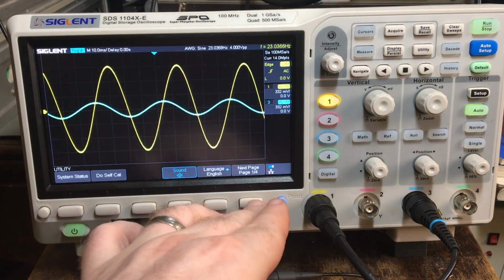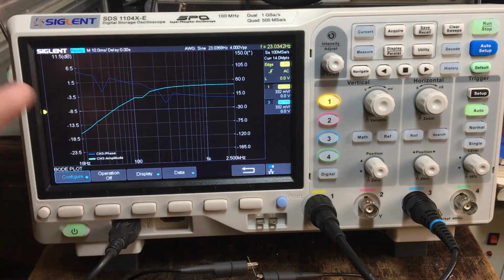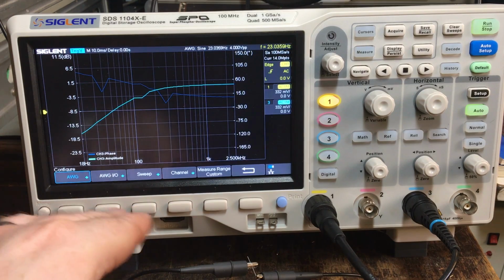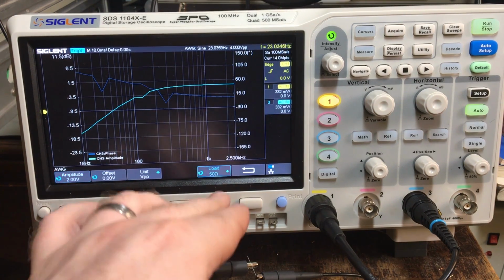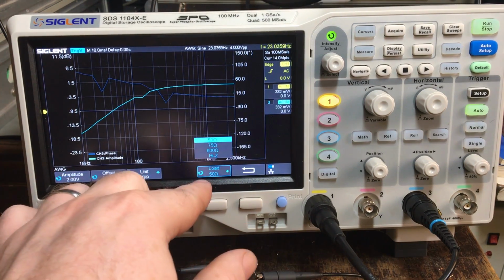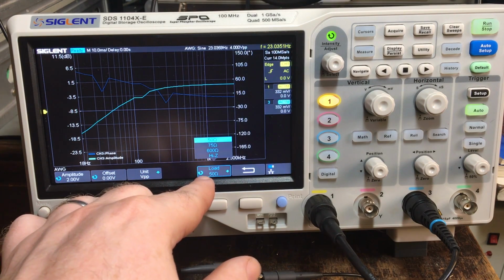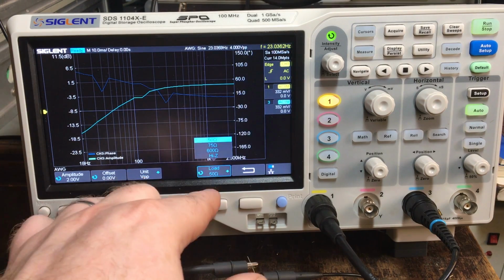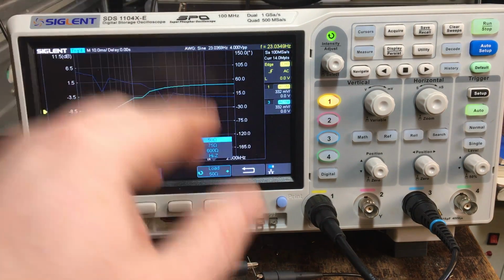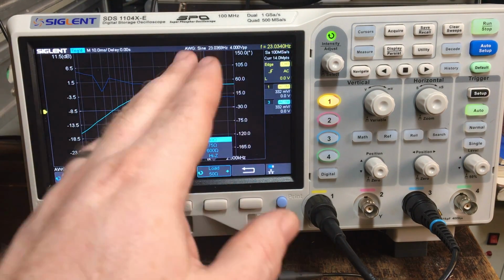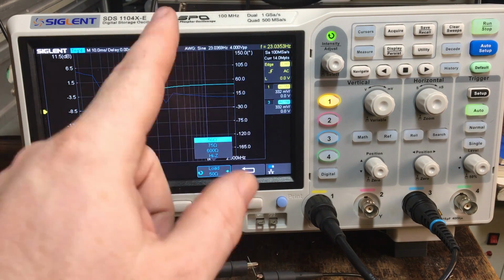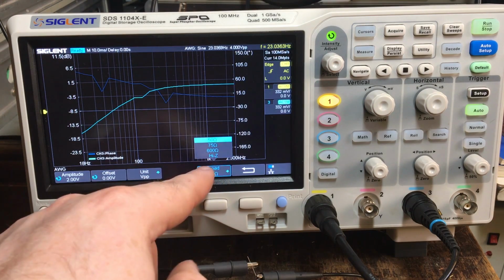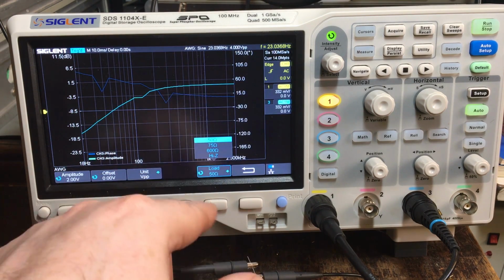There may be a reason for that, or maybe I'm missing something, but that's my understanding right now: if you're trying to set this load option, although there are multiple options here, and there's even an adjustable one here, in theory you can set any value between 50 ohms and infinity, high Z. But it doesn't actually take that setting. 50 ohms takes and high Z takes. Those are the ones that work. So choose one of those, right?